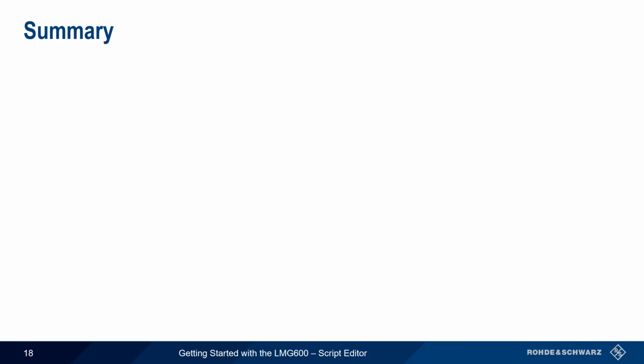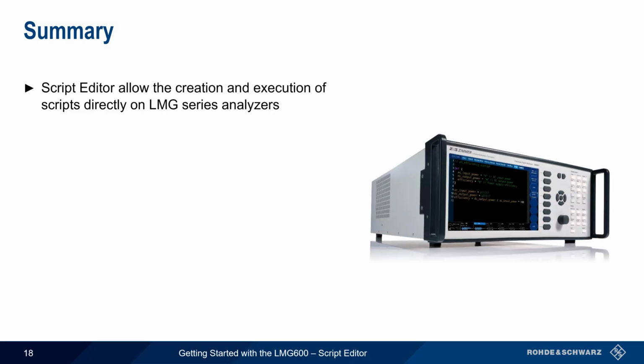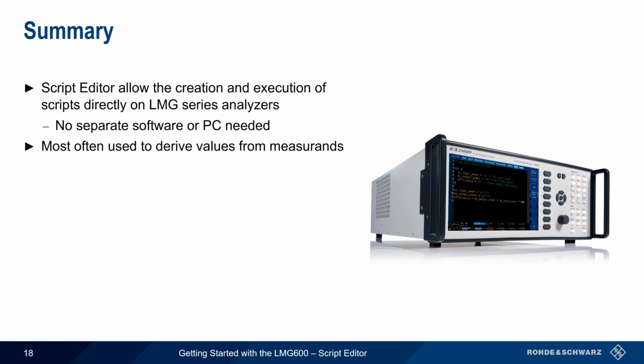Let's end with a brief summary. The Script Editor feature allows scripts to be created and executed directly on LMG600 series analyzers without the need for any external PC or software. The most common application of Script Editor is calculating or deriving values from measured values or measurands. For example, using measurements of input and output power to calculate the efficiency of a power supply. The numerical results produced by Script Editor can be used in the same way as other measured values, and can be displayed, plotted, etc. in the same way as well.